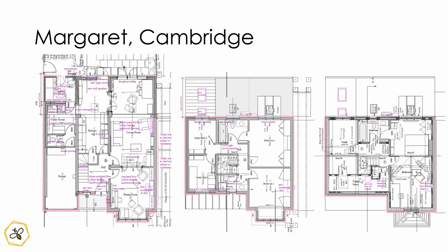If you go for 10 kilowatt, there is a very nice system that Mitsubishi make, where it's actually 2 5 kilowatt heat pumps working in tandem, so that most of the year only one of them is working, and then when you get the cold weather, they both come in to cope with that heat loss. But is the outdoor unit double size? Because we're a little tight. I could get a standard 1200 wide, but if it's a great big double unit, I'd have trouble with that.